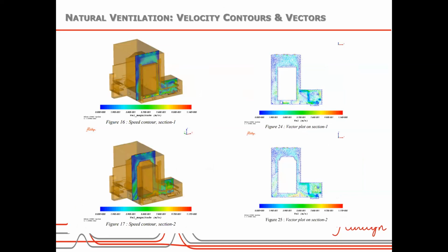We just solve the Navier-Stokes equations coupled with the pressure and also the energy equations with the turbulence model. These are some cut sections of velocity contours we have made for different sections, showing how the velocity distribution is in the domain. We can see that because of heating, the air is entrained from the side inlets and escapes through the outlets.